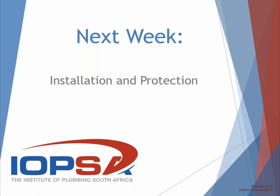So we will ask the question, and then the onus will go back onto the plumber to show that this particular lagging he has used is in fact R1 rated. It might be an exotic material that I've never seen or heard of, and I get educated, and I'm happy for that. But I will still ask the question and say, I don't know this R rating, I'm not familiar with it. Please show me the calculations. Please show me the spec sheet, and that'll have to then prove the case.